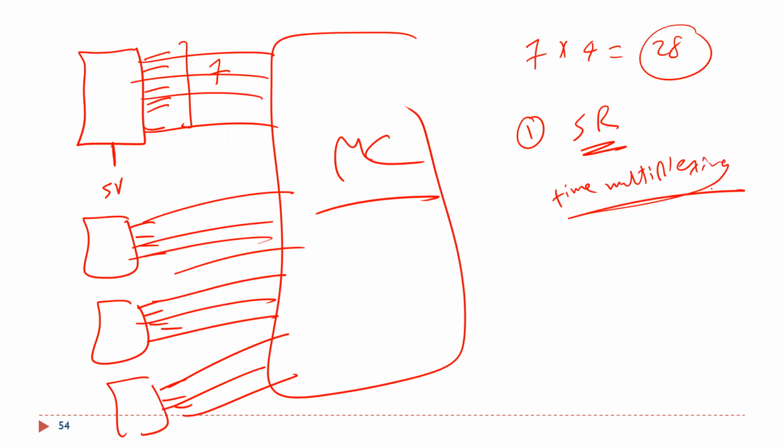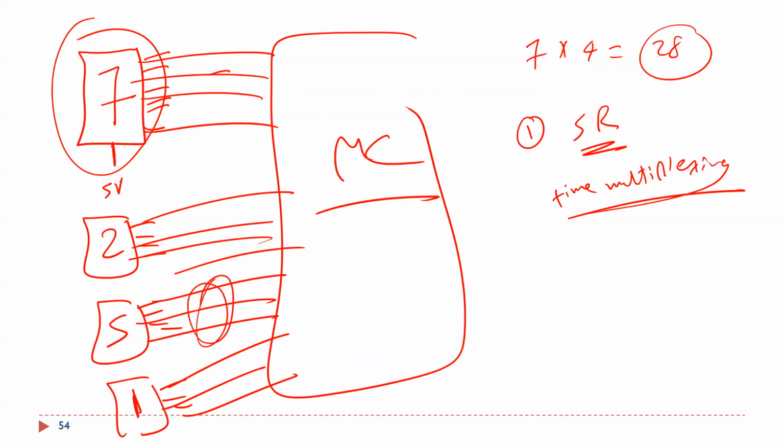I'm going to tell you what this means, but listen to me first. Look here, guys. If I want to display a number, for example 7251, then with this connection the 7 is going to be displayed all the time. If you put 2, it is displayed all the time. If you put 5, you have to put some zeros and ones to display 5, and some zeros and ones to display 1. All of them are displayed all the time. Is that okay? We can do better than that.